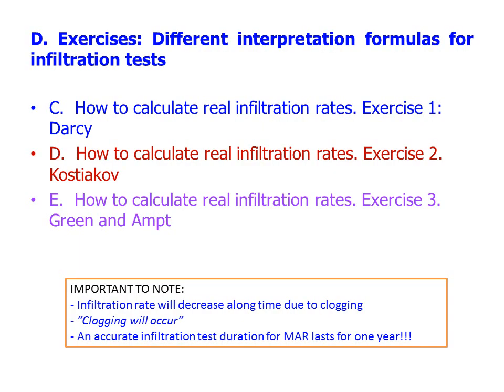It is usual to find problems during the interpretation of infiltration tests. This is why we have proposed a set of 3 different exercises applying 3 different methods. It's important to note that the infiltration rate will decrease along time due to clogging. Clogging will occur, and an accurate infiltration test duration for MAR may last 1 year.